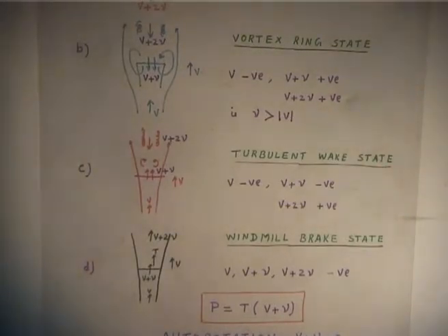Now, is it clear? What we will do is we will first derive the inflow, assuming that the expression is valid for all conditions. Please note that I am making an assumption, and then we will plot that result on a curve, and that is called the generalized, or you may call it universal inflow diagram.